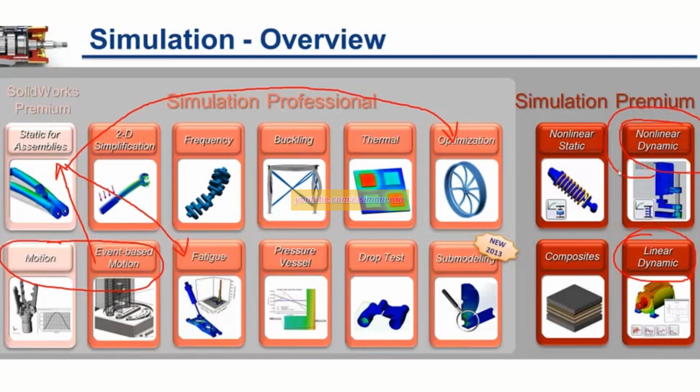Next, we're going to overload, so we're going to assume that our linkage or our mechanism, in this case our landing gear, is stuck and the actuators are firing off a full load. So if the mechanism can't move and we fire up our actuators, are we going to get permanent deformation? And how much permanent deformation? And that falls into a nonlinear static load case.